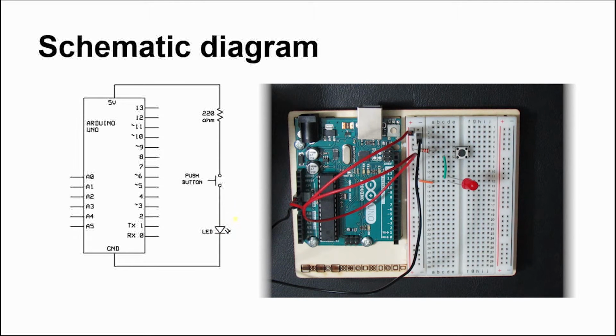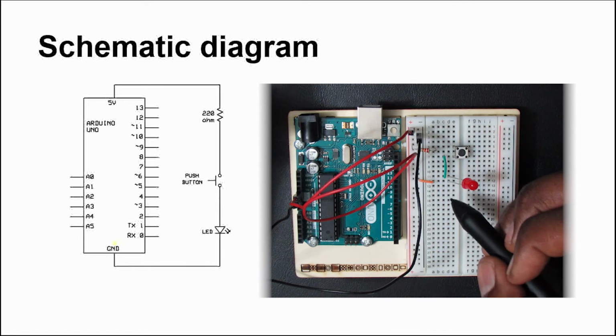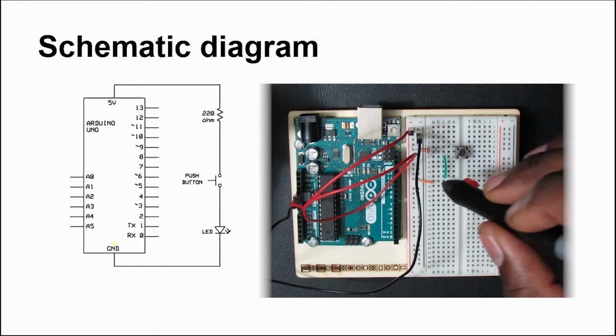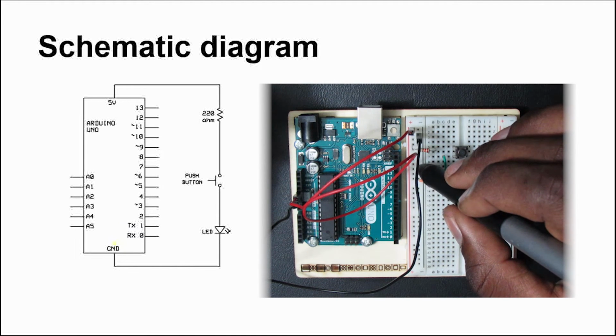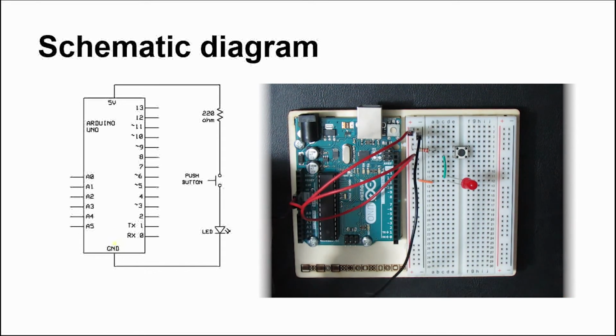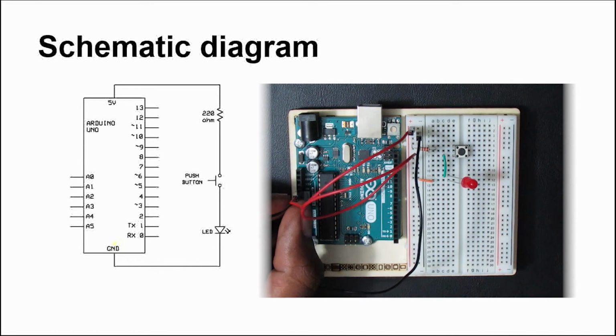Okay, so coming out of the cathode side, we end up back here at ground. So from here, you go back into this jumper cable, and then the jumper cable is connected to the negative part of our power bus line, and then out of here you see the black wire go back into ground on the Arduino board. Okay?